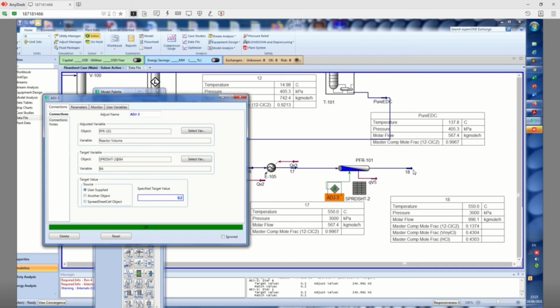We decided to separate these three components using a distillation unit operation, but we can give some justification why we should go for distillation instead of other separation techniques. For that we have to look into the fluid properties. I will show you in the next lecture how to check the fluid properties of the different components, here vinyl chloride monomer, hydrochloric acid, and ethylene dichloride.